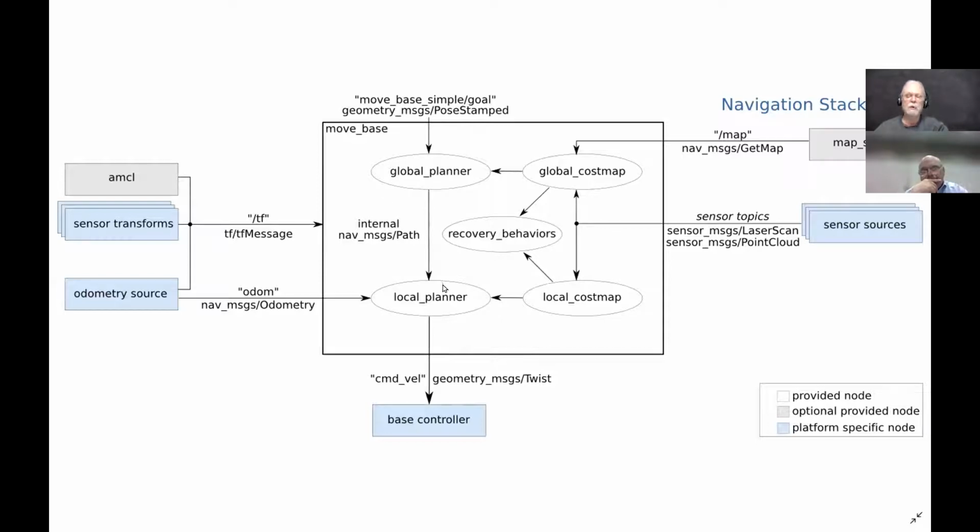The final outcome of this whole thing is it generates this command velocity message. That's what actually goes out to your vehicle and says, drive forward this fast and control the steering like this. And again, as we've mentioned multiple times, the standard command velocity uses rotational velocity to define your steering. The modified command velocity in TEB Planner uses a steering angle that they wedged into this, so it becomes a modified command velocity. Or you can run an Ackermann message.